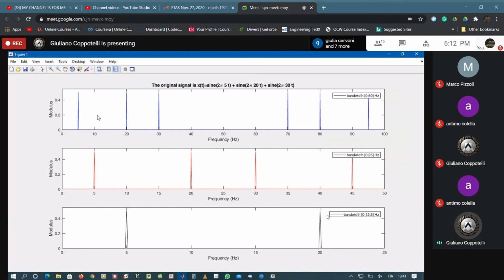The second line, the center one, has, remember, a downsampling of 2, so our sampling frequency is lowered from 100 to 50, and therefore the maximum frequency would be 25. As you can see, the decimation technique, the resample, is correctly taking into account only the two frequencies that are in the frequency range 0 to 25. So we clearly see the frequencies at 5 Hz and 20 Hz. Of course, we do not have any good information for frequencies higher than 25 Hz, although there is the mirroring of 20 Hz with respect to 25 acting at 30 Hz, but that is a wrong identification because, remember, this center plot is good up to the maximum frequency of 25.